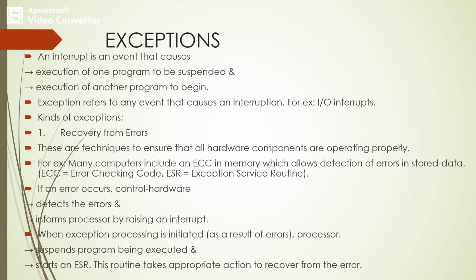stored data. So we can also use ESR, that is exception service routine. If an error occurs, control hardware detects the error as well as informs the processor by raising an interrupt. When exception processing is initiated as a result of errors, the processor will suspend the program being executed and start the exception service routine or ESR. This routine takes appropriate action to recover from errors.